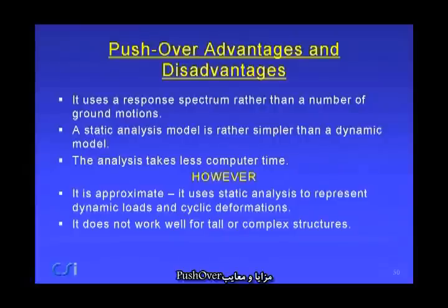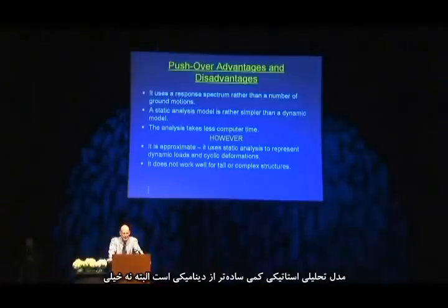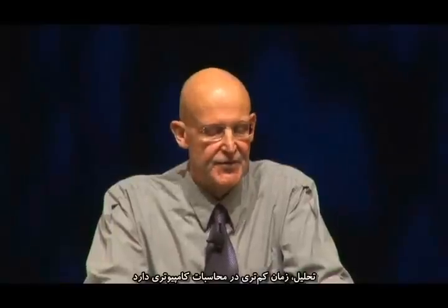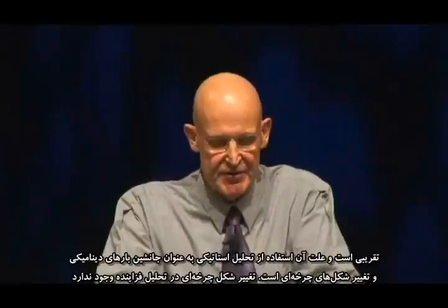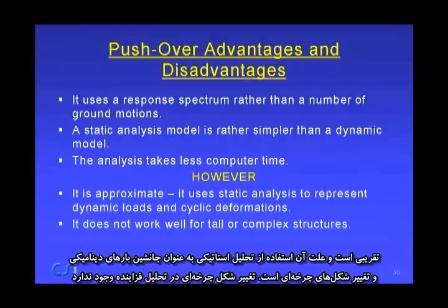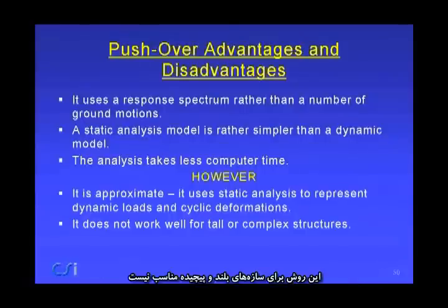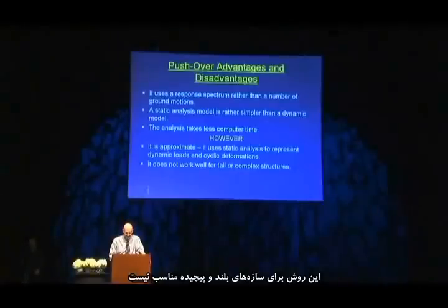Advantages and disadvantages of pushover: it uses a response spectrum rather than ground motions. The static analysis model is a little simpler than dynamic, not a lot, but somewhat simpler, and the analysis takes less computer time. However, there are major caveats. Firstly, it is approximate, and the reason is it uses static analysis to represent dynamic loads and cyclic deformations. There's no cyclic deformation in a pushover analysis. And it does not work well for tall structures, and it doesn't work well for complex structures.